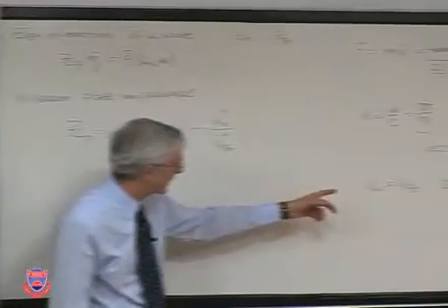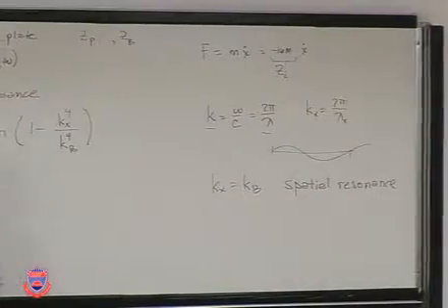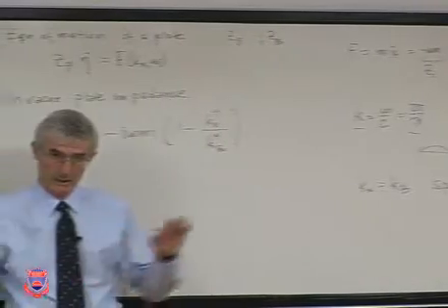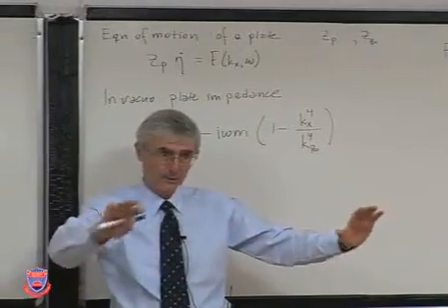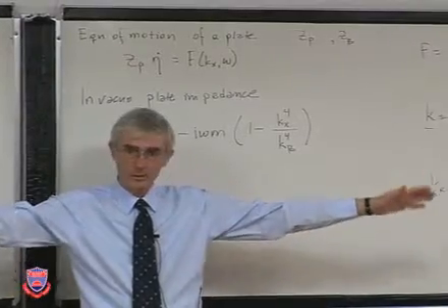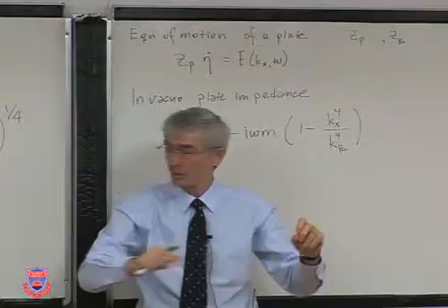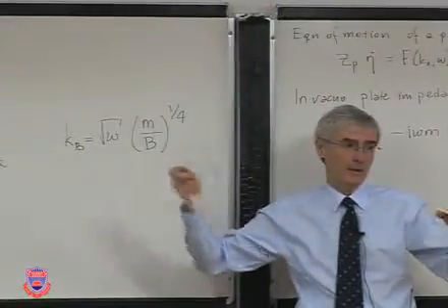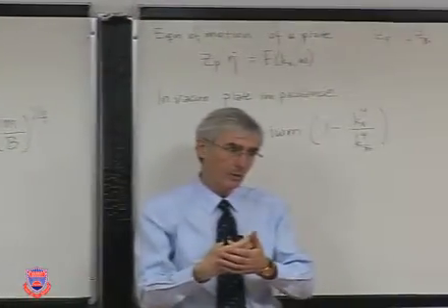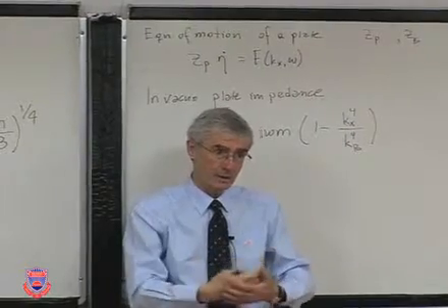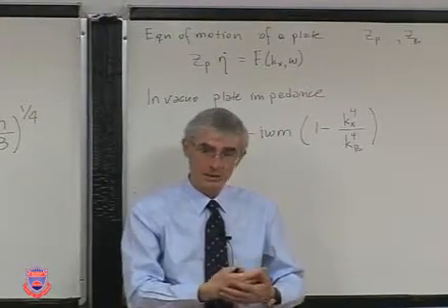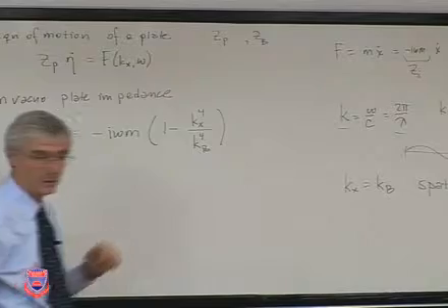But this Kx comes from the forcing. The force that comes onto a plate has its own wavelength distribution. If that wavelength distribution and the free bending wavelength correspond, then you have a resonance. It really then vibrates immensely. Impedance goes to 0.